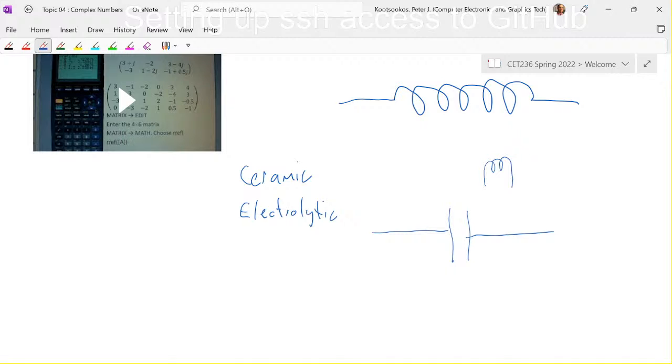The reason they explode is usually because those also have a voltage rating, which is probably 16 or 25 volts. I've forgotten what these ones are. If you connect up 50 volts DC to them, they will explode if their voltage rating is 25 or 16 volts. Okay?